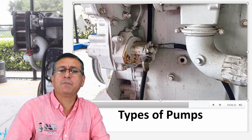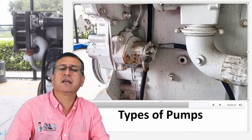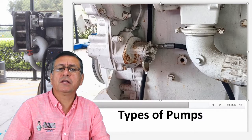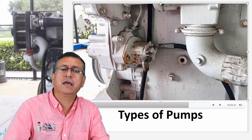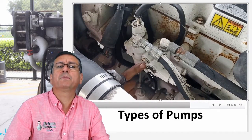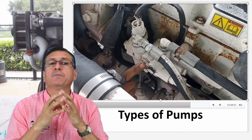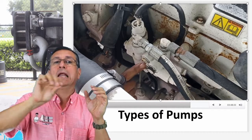This is a mechanical pump. The gear here is connected with the gear of the crank, but this is for high pressure. The input enters here, and the fuel goes over there and enters this pressure regulator. This is the pressure regulator. That element controls the pressure before the fuel enters the fuel common rail.